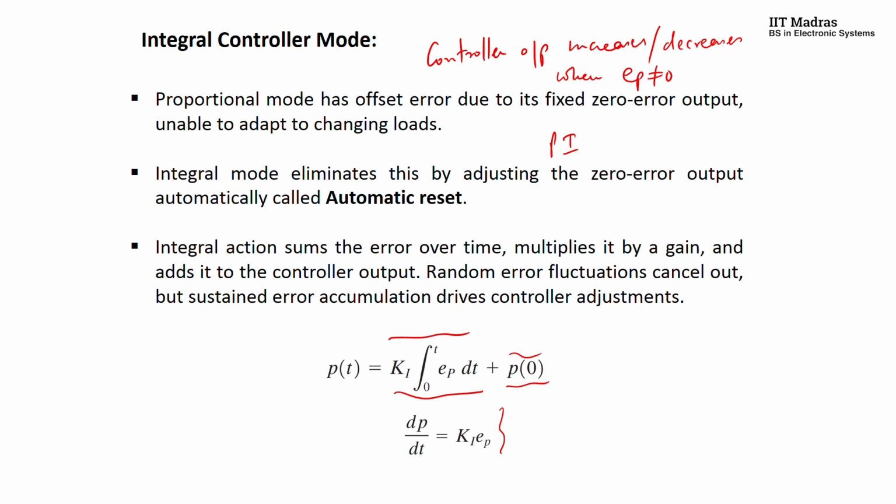What do you mean by reset? Reset means that for every steady state load change or every permanent load change, you should be able to get back to normal, in the sense that we need to get back to zero error condition. That is ensured by the integral controller, since if the error is 0, the integral controller will hold the last value, and therefore it would ensure that error goes to 0. That's the main advantage we get from the integral control mode.